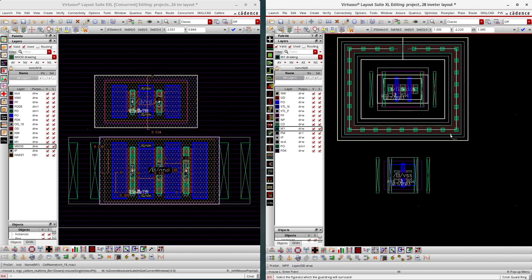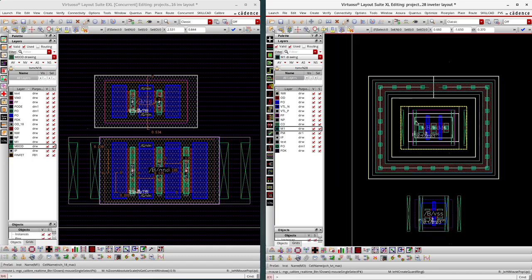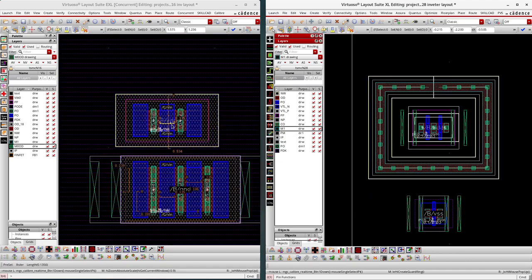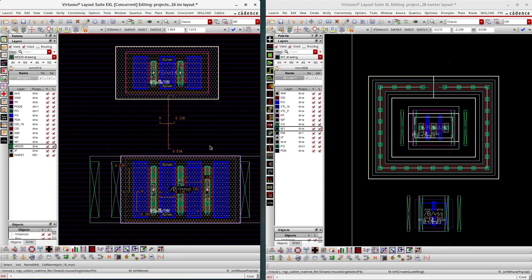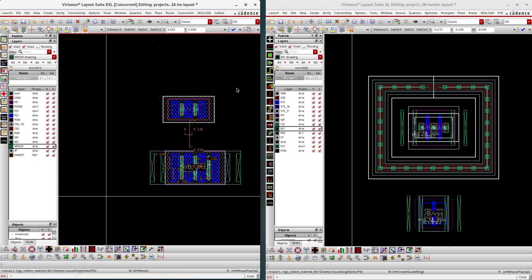So here in our planar MOSFET, we have only the OD layer and the M1 layer. Hope you can see here, the guard ring consists only of the OD layer, okay. We don't have any poly in the guard ring. But if you come to a FinFET device, this is our FinFET device, whatever I have here. Let me clear the markers. This is our FinFET device.